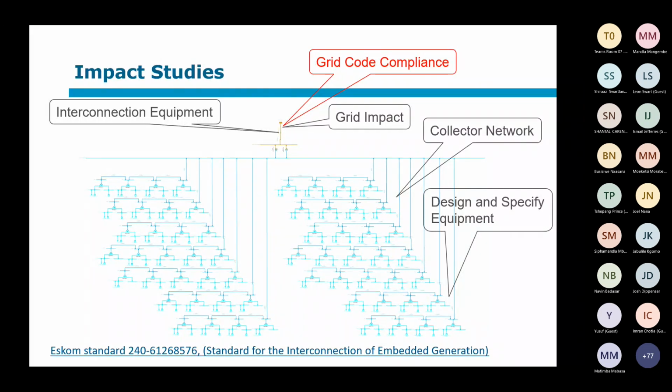Okay, now, what is your responsibility when it comes to the generator network design? The interconnection equipment, that's important that you speak to each other and make sure that you've got that correct. The power quality, they don't need to simulate that anymore. Originally, there was a request that they simulate this. The only thing that needs to be checked is resonance screening. And that's typically due to all the cable capacitance. And even if they add capacitors, you don't want a resonance condition on your network.